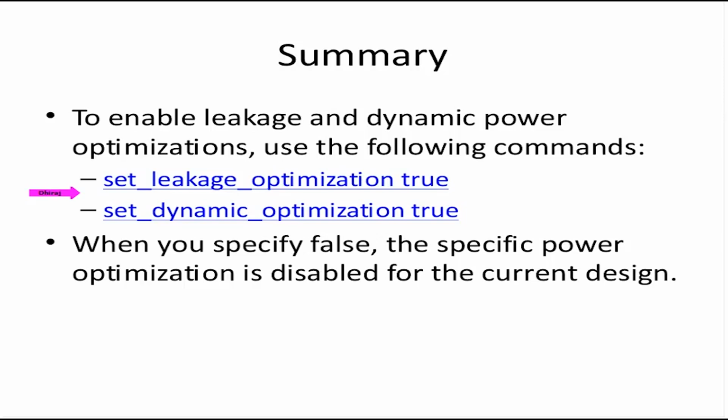The next step would be in one of your simulations. You must be doing some kind of simulation of some design in any other course. Dump out the VCD, generate an SAIF, read back the SAIF in Design Compiler, and do a report power. You should do all these things to understand the concept better. Right? Thank you.